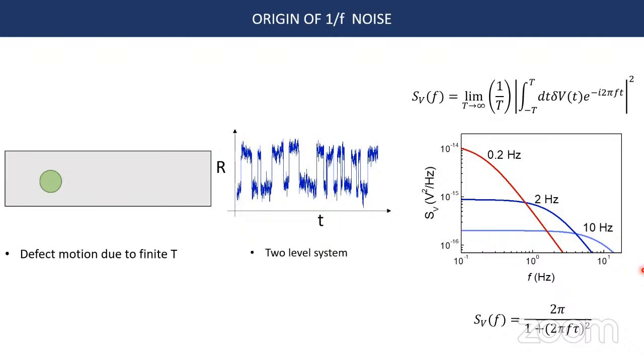Okay. But of course, if you have some trapping, detrapping, there would be phase noise involved. We have typically not included the effect of phase noise here. We have primarily concentrated on the autocorrelation function to extract the noise amplitude, the noise magnitude. Okay.